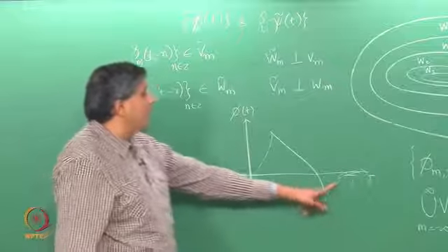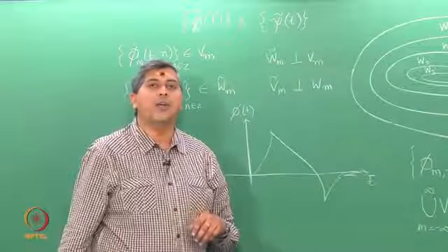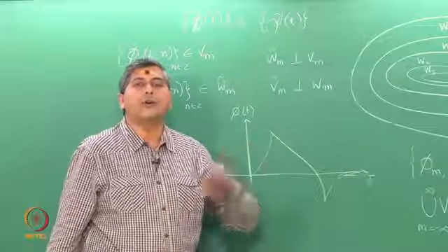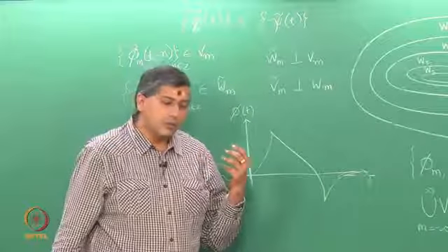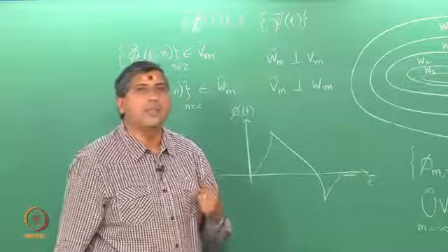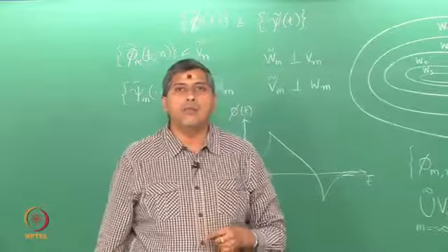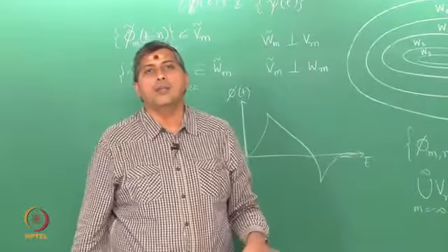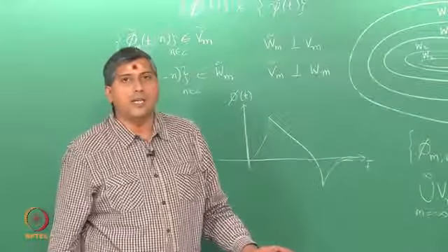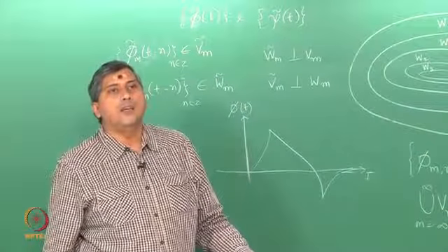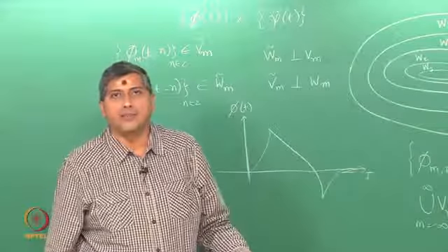Now, you can see that this scaling function is not symmetric. In fact, the associated wavelet is also not symmetric. So, what happens if there is no symmetry? Remember, I am using wavelets as filters, and whenever I filter a signal, the phase of the signal is altered.